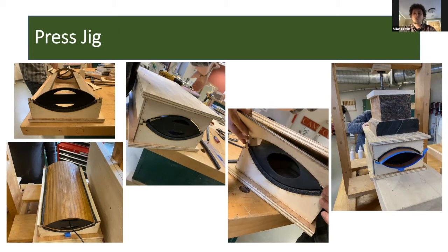We left an overhang on the outside of the veneer so that we'd go back later and use fine handwork once we take it out of the jig, to ensure that the quality control would be at its finest. And the constant pressure was delivered to the top of the jig, and this was a twist clamp.